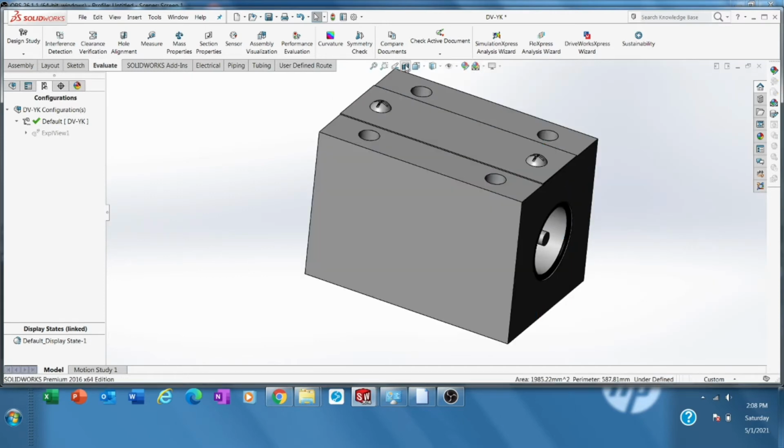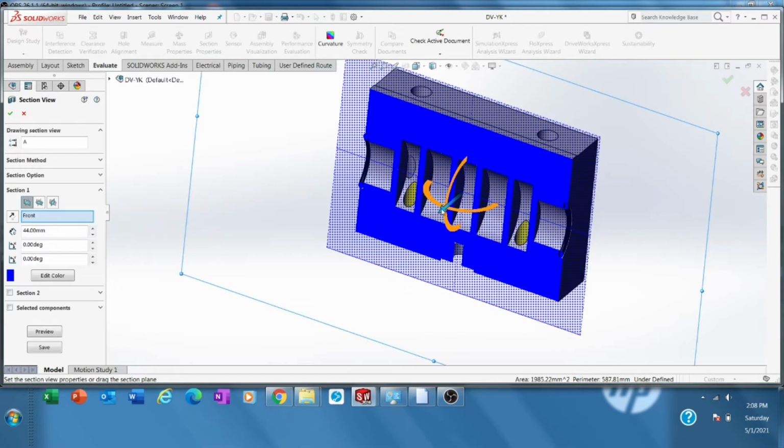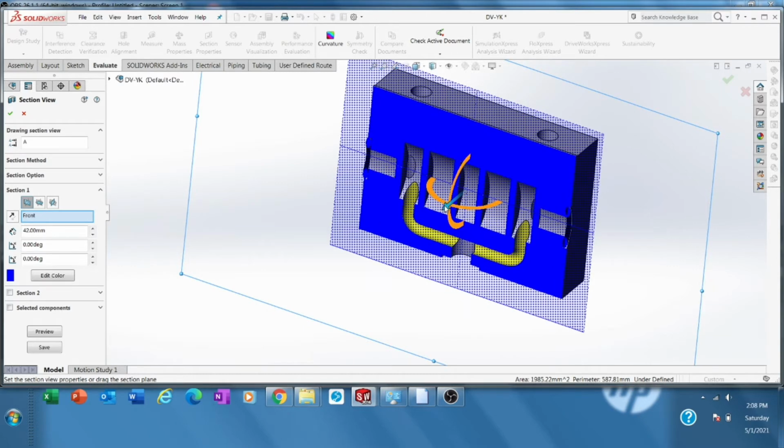Let's check in another way, to make it a bit simpler. So now I think you understand how it manipulates from either position. When the pump operates, there is no spool movement. We call it closed center. There is no flow to port A and B. It stays there forever, whether the pump is on or off. The balance of the force will be there.